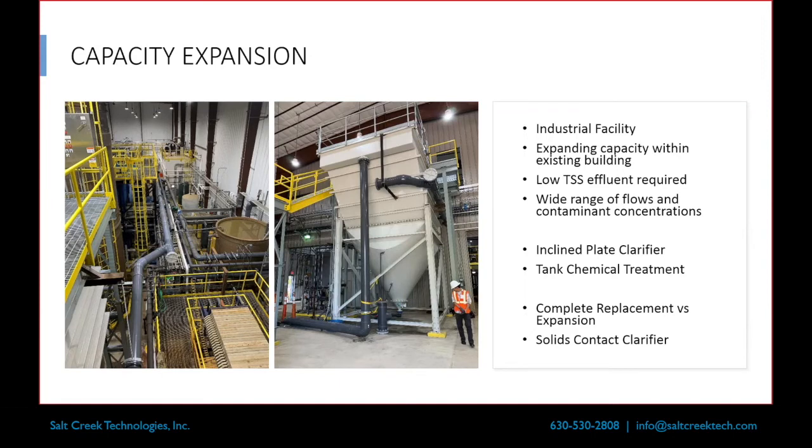Went through the exercise of looking at doing a complete expansion or a complete replacement versus just an expansion as well. Part of their thoughts were that maybe they should look at a solids contact clarifier. So we alluded to this a little bit of taking some of that sludge back to the front of the plant to try and help give more opportunities for those particles to form larger particles so that you can actually get better treatment. So we took a look at all those things.